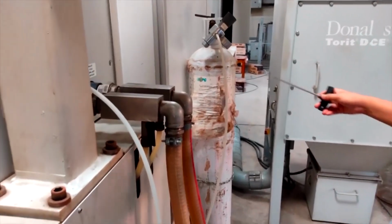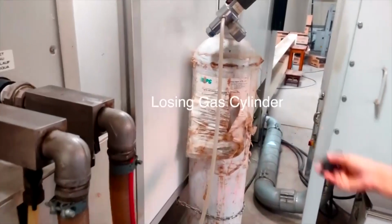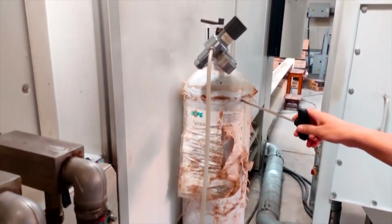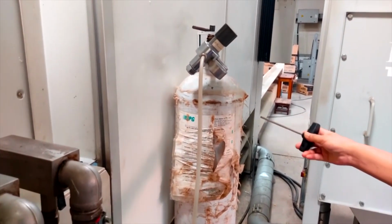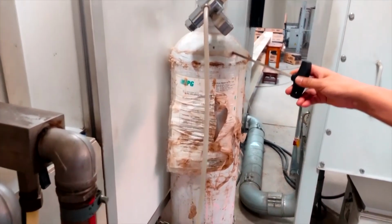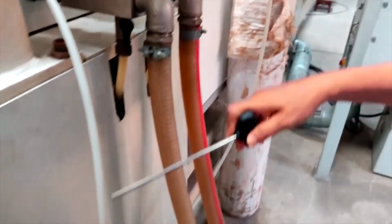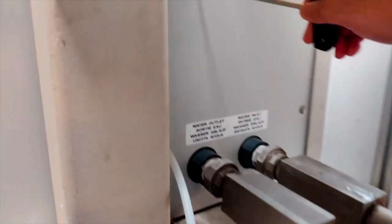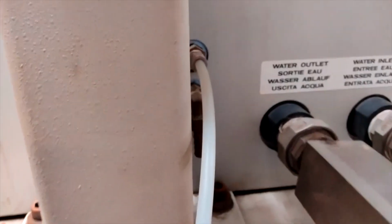This is the CO2 gas cylinder, that is, the lasing gas cylinder. It has the proper proportion of the lasing gas, and through this lasing gas only we are generating the laser beam. Now the CO2 gas will be transferred to the resonator through a pipe.